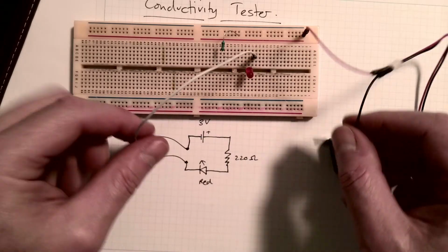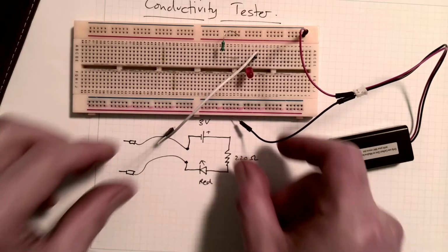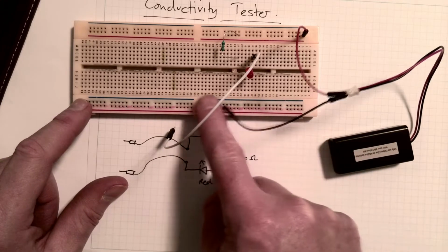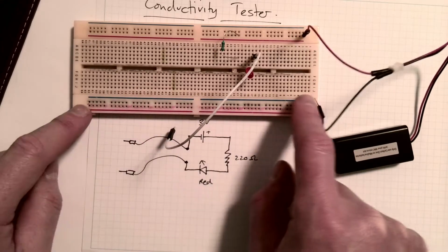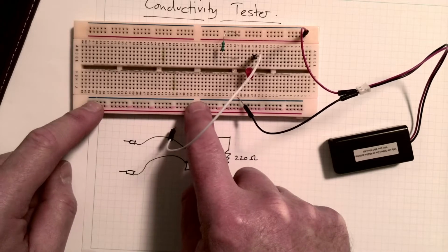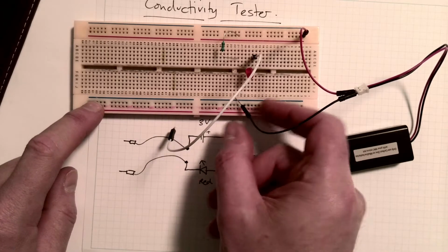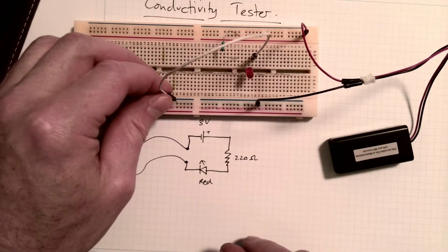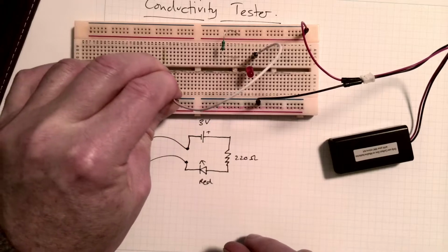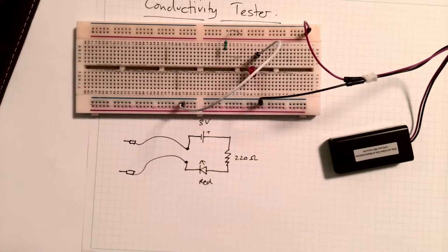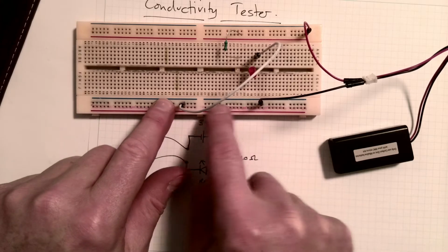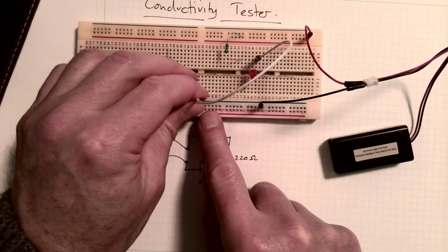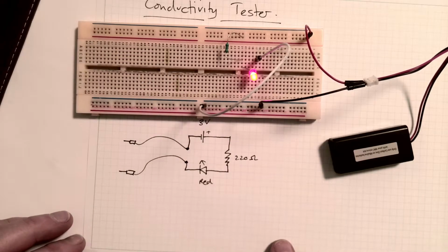So what I can do is take different materials. For example, in the circuit board, remember we had the question whether this rail here was connected to this rail here. See the blue rail here, the blue rail here. There's a gap between those blue rails, so that suggests that it's not connected, but it's always worth checking. So I can stick that in there and stick that in there and discover that it's not connected. Some of them are a little bit stiff. There you go. So these 2 rails are not connected, whereas this hole down here is connected, and we can see that with our light.